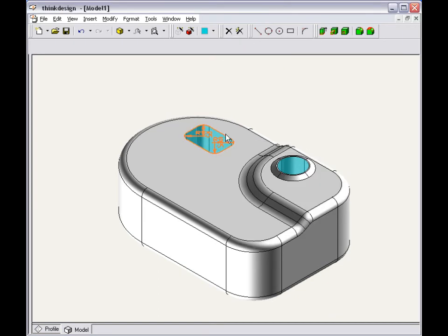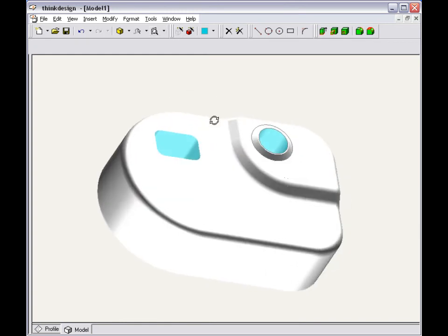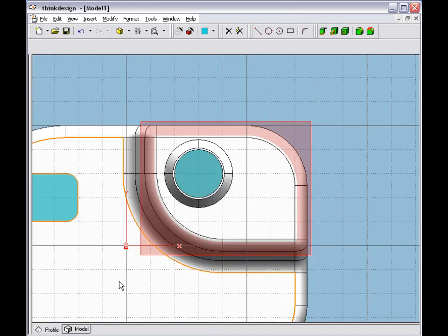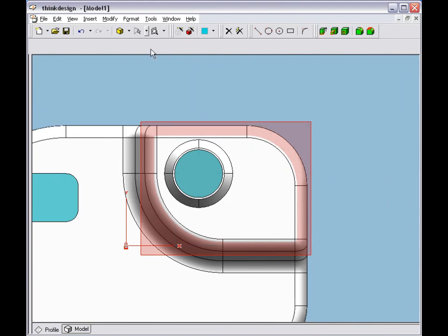We now hide the support geometry and rotate our model to have a first view of what we have done. We forgot the viewfinder, among other things. As usual, we place our work plane and we sketch the shape of the viewfinder. This time we need to disable the grid to be able to position our geometry freely without constraints.